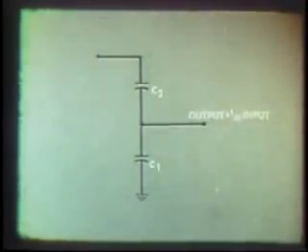Capacitors C1 and C2 by themselves also form a voltage divider. If their values are of the right ratio, they can also divide the voltage by 10 to 1. A capacitor's reactance, of course, changes in relation to the applied frequency. Since both elements of this divider are capacitive, they will both change in proportion to the frequency, and the ratio will remain the same. Therefore, they will continue to divide by 10 to 1 even when the frequency is changed.